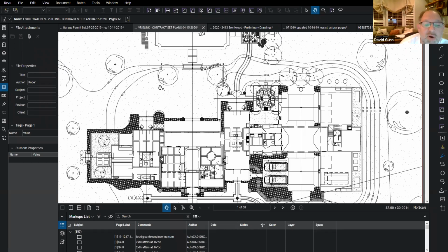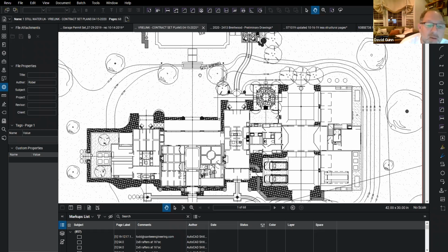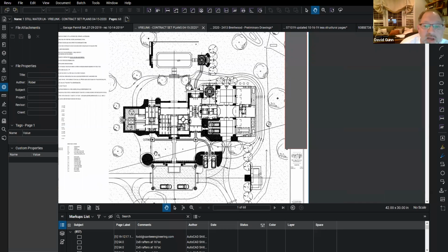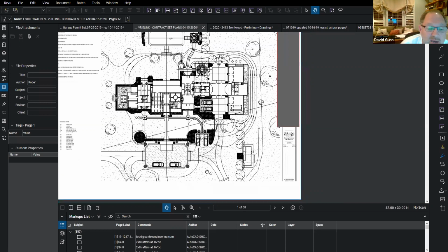So it shows us how the ground is sloped around the property. This is also showing us where trees are, these little indications. A dot with this space around it is his indication for a tree. That may mean a tree we need to protect. It may mean that it's a new tree. We may have to dig into that to find out exactly what that is, but that's their indication.